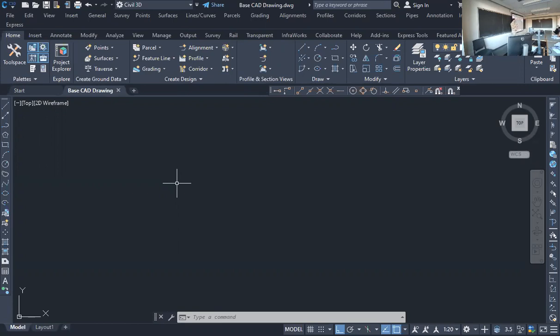Yes. So 1 through 6 or 10 through 20 or whatever you numbered them, they're already in there. So the file you import, you might want to do a save as of it and erase those points because you can't duplicate them. They're already in there. So either go in and erase them.